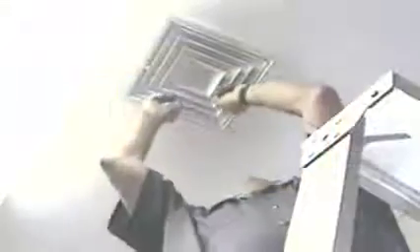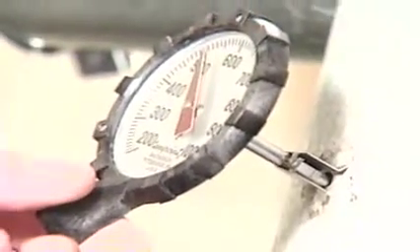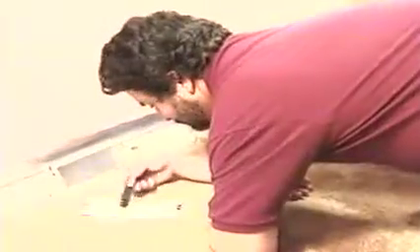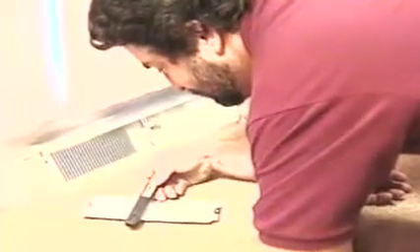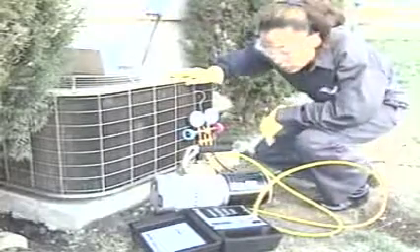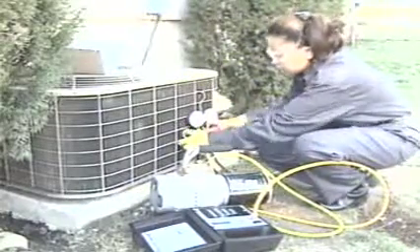So it's important to test the system after the repair to make sure the problem is solved. It's the best way to keep your customers happy and to avoid expensive and unnecessary callbacks. Testing a repair often means you'll need to wait a short time on site to make sure that correct temperature ranges are achieved. For example, testing the temperature rise of a furnace or the temperature drop across an evaporator coil. In some cases, you may even need to leave and return later after several hours to check on a system.